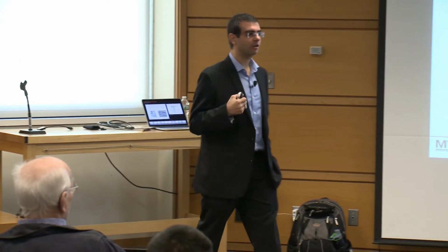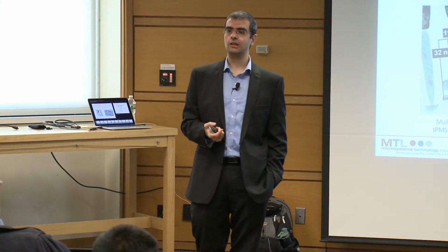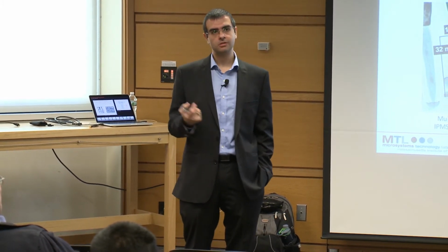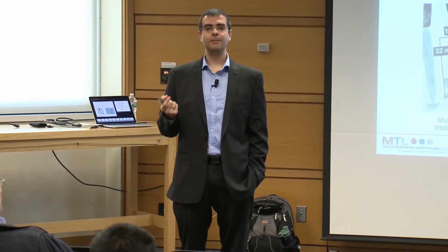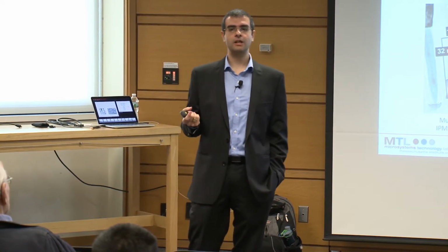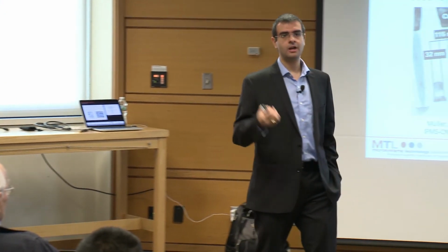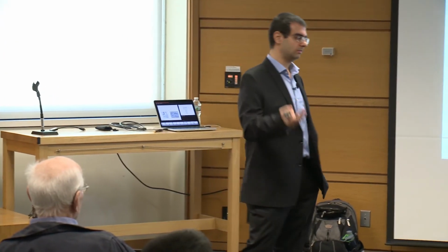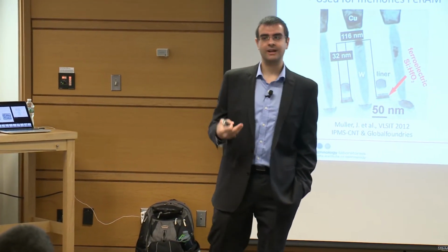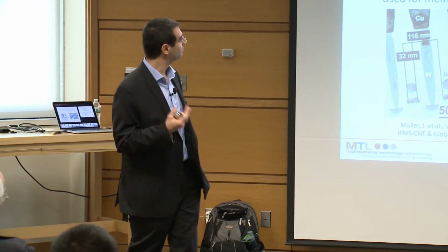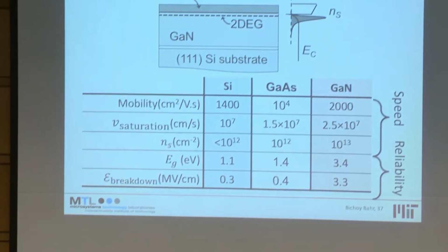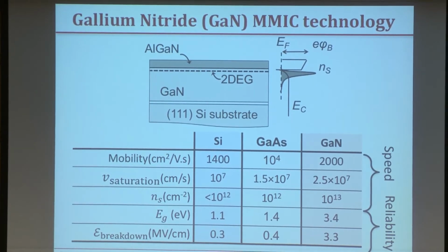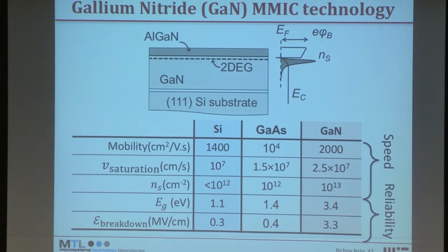But we started thinking, okay, if we need piezoelectric transduction and we are stuck with CMOS, well, it's fine. But what happens if we move away from CMOS? There is actually a very nice piezoelectric material that happens to be also very nice from an electrical point of view, and it's widely used today for RF circuits and power applications. And it also has its integrated MEMS technology. I guess you can now see what material I'm talking about. I'm talking about gallium nitride. So we said, okay, fine. If it's a little bit hard now for piezoelectrics in CMOS, why not use gallium nitride?